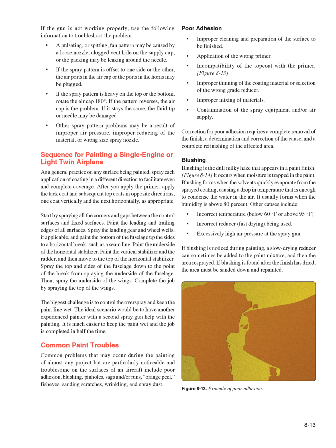Poor adhesion: improper cleaning and preparation of the surface to be finished. Application of the wrong primer. Incompatibility of the top coat with the primer. Improper thinning of the coating material or selection of the wrong grade reducer. Improper mixing of materials. Contamination of the spray equipment and or air supply.